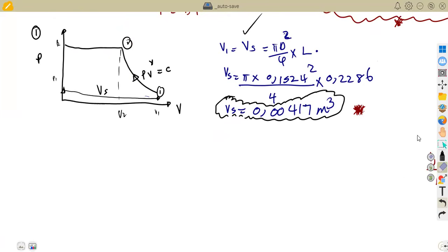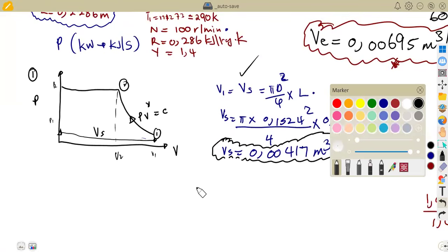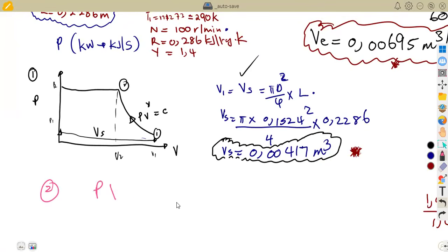So this is it. How do you calculate the mass? Remember, this is air compressors, just like gas. We know that PV can be used to calculate the mass. So from the PV equals MRT formula, I'm going to take P1, V1, T1 to calculate the mass. Like I said, if this mass is just in kilograms, not kilograms per second, meaning kilogram per cycle, you use V1, which is just cubic meters per cycle, which is our VS. Remember, V1 is equal to VS if there is no clearance.